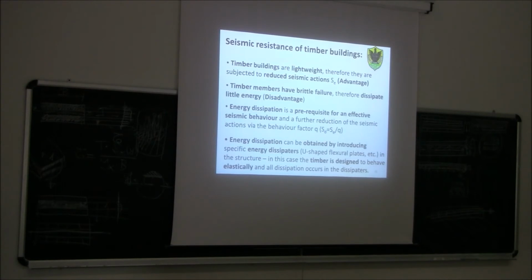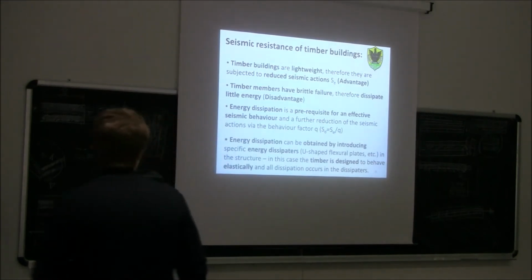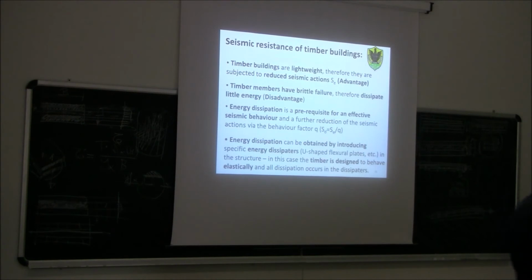However, I add some devices in different locations that are able to dissipate energy. So in this case, I get the energy dissipation that I need to reduce the elastic forces by the behavior factor by locating in certain points of the structure some energy dissipators.